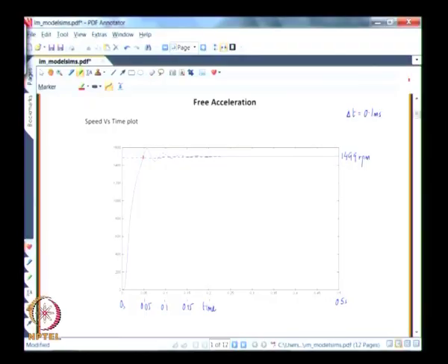But the rotor having reached synchronous speed here, it has been accelerating all along and there is a momentum that has been gathered. So that momentum takes it beyond synchronous speed, and once it is going beyond synchronous speed the retardation force sets in, and therefore the rotor now decelerates and reaches synchronous speed here, and then it undershoots as well because it is now retarding, then it accelerates again, and finally these oscillations damp out and it settles down at this value.